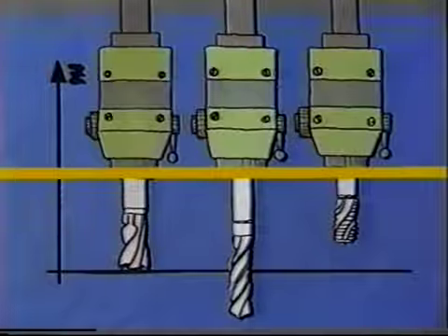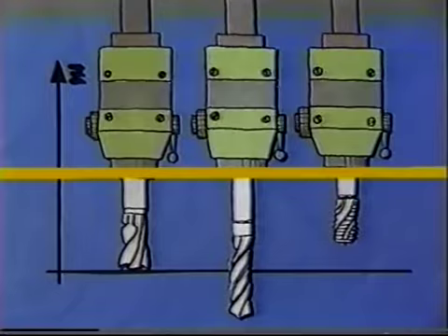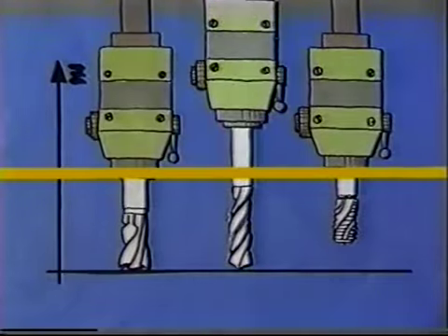It has to stop before that happens. In other words, the position of the spindle nose in the direction Z plus must be corrected. The compensation value is exactly equal to the difference in length. If a tool is shorter than the zero tool, the correction must be in the direction Z minus.